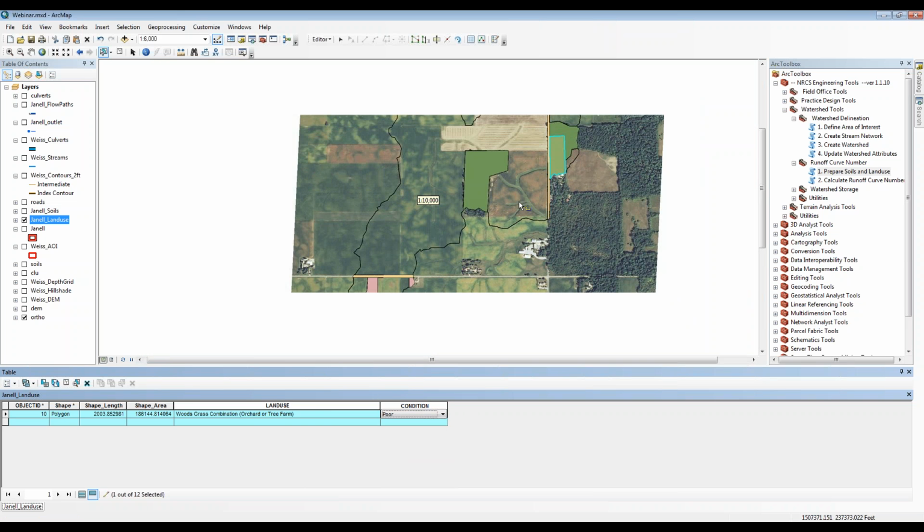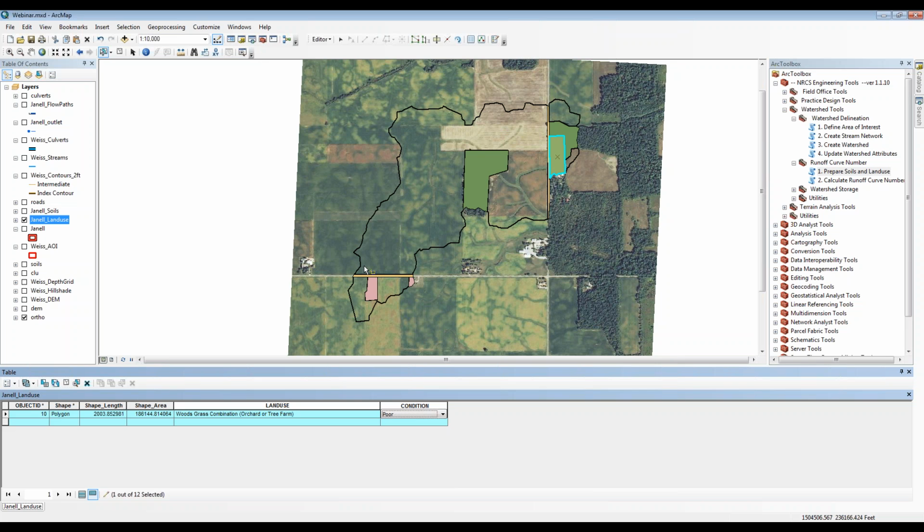All right, the last thing we have left. I haven't looked at that, but I assume that the land use and the conditions follow the EFH Chapter 2 guidelines. What do you mean, Justin? Well, the conditions apply to some of them, but some of those categories don't have conditions associated with them. Yeah. Like the farmsteads, it's just a curve number. But woods has them, and obviously there's more detail on the crop fields. Are the numbers behind the land uses the same as the EFH2?